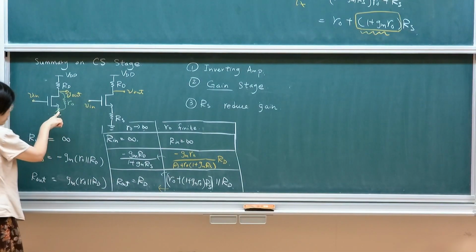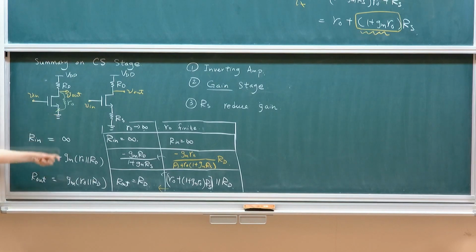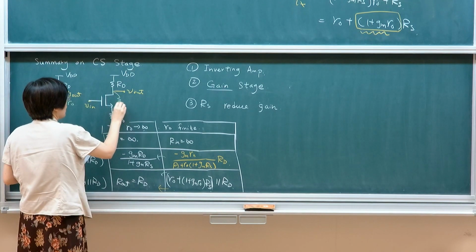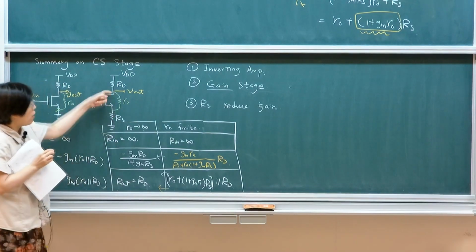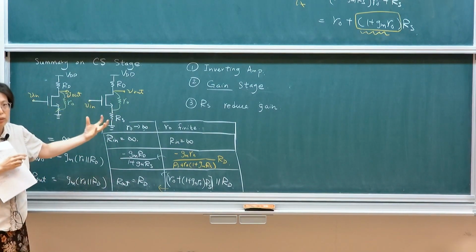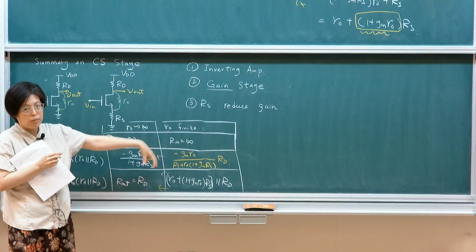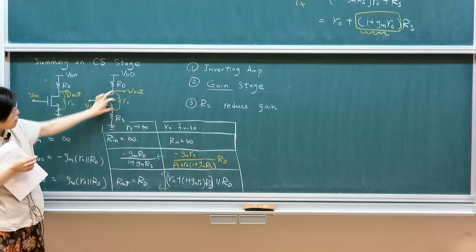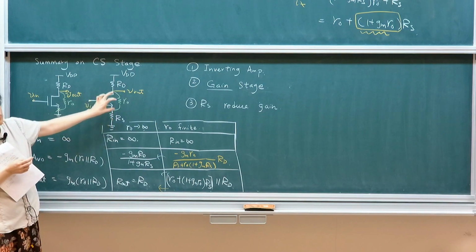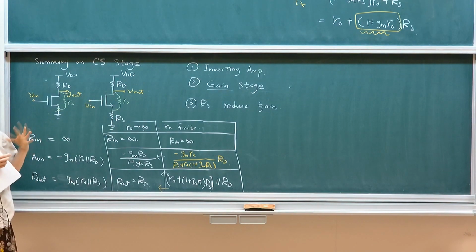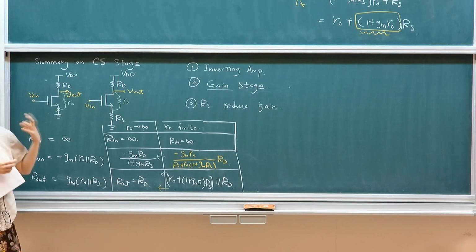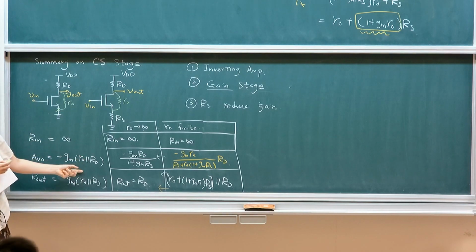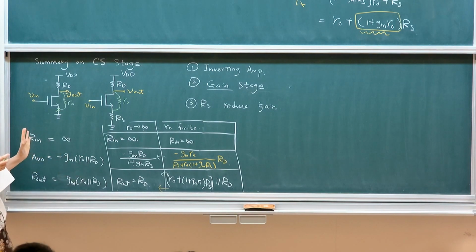So if any one of the terminals is ground, then it's easy to include. If neither terminal is grounded, then including it causes a lot of complications because of the feedback: the bridge between them will affect the voltage and then it will feed back to the circuit. That is why it makes much more difference. If one terminal is grounded, it's just a parallel capacitor or parallel resistance, so it's much easier.